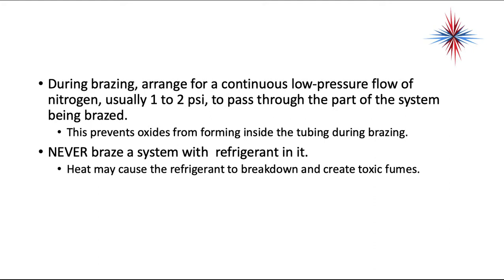There are some newer systems out that use butane, propane, and other combustible gases as high efficiency, low ozone depletion, low global warming refrigerants. If you see a tag that has one of the newer refrigerants, make sure you're aware of what it is before you braze it. It can explode.